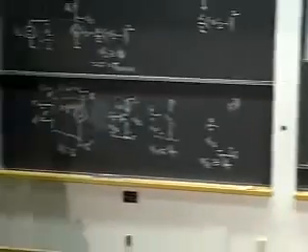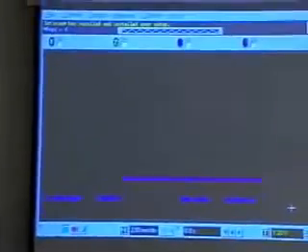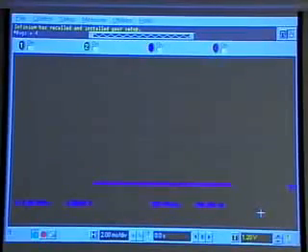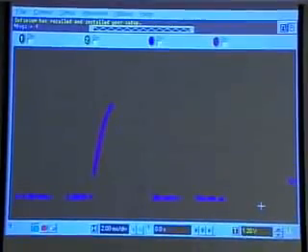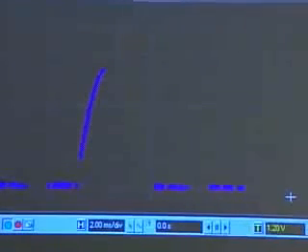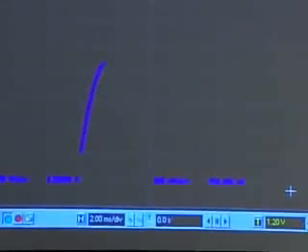And we also had some fun and games here. We said, what if I turn VGS off? Boom. That would be my IDS of 0, implying that the MOSFET behaved like an open circuit between the drain and the source. I applied a positive VGS, more than VT, and it began to look like a resistor. Open circuit, resistor. Open circuit, resistor. Up to now, nothing new. You shouldn't have learned anything new until now in today's lecture.